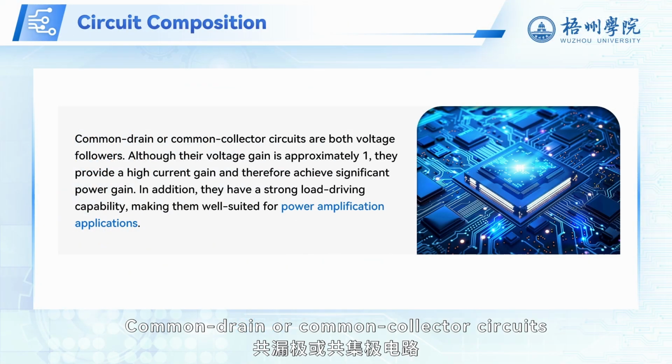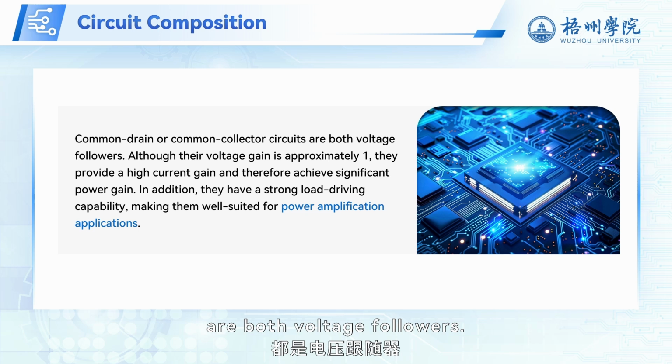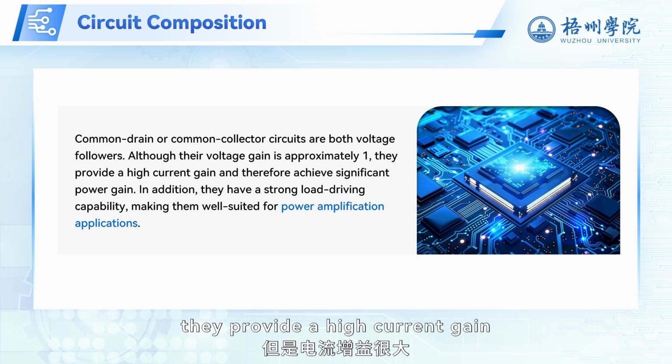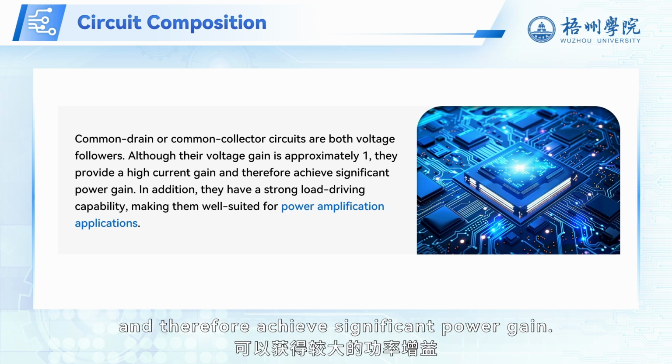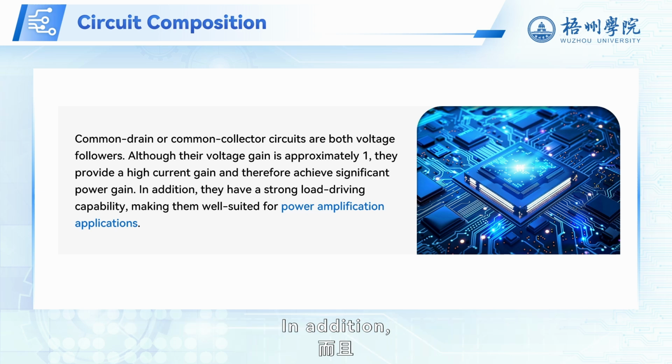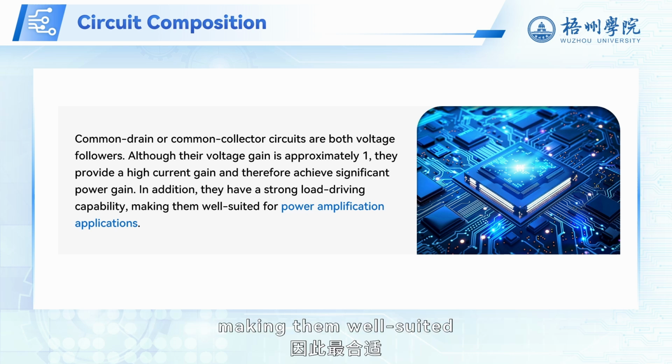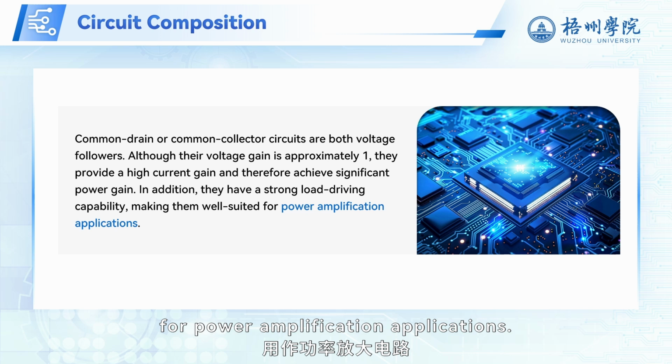Common drain or common collector circuits are both voltage followers. Although their voltage gain is approximately 1, they provide a high current gain and therefore achieve significant power gain. In addition, they have a strong load driving capability, making them well suited for power amplification applications.